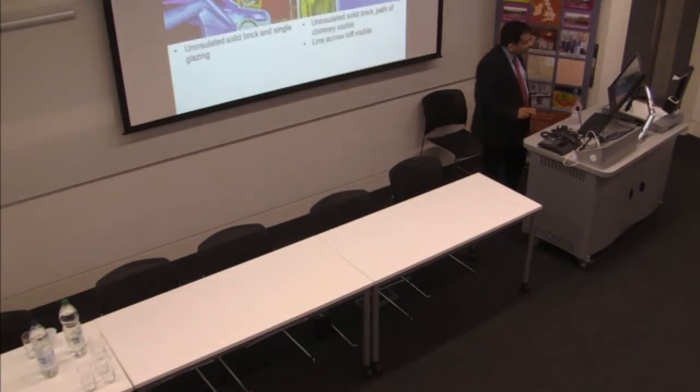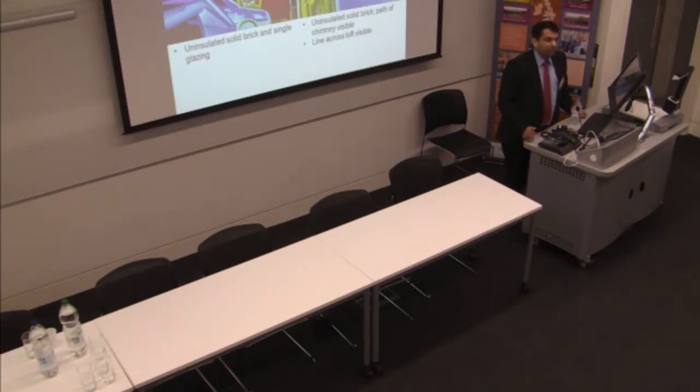Okay, moving on. Let's look at the effectiveness of fabric upgrades. Thermography here was very helpful, and I think it does two things. One, it's an engagement tool. So even if it's not the most accurate and you don't set the camera right, it's okay because it can actually help you in engaging people. And that, I think, is an important function. The other function, which is more technical, is diagnostic: to find out whether the intervention that has been made is actually delivering the savings and whether it's been done properly or not. I think it does both things, so we've used it as a diagnostic tool and also for raising engagement.